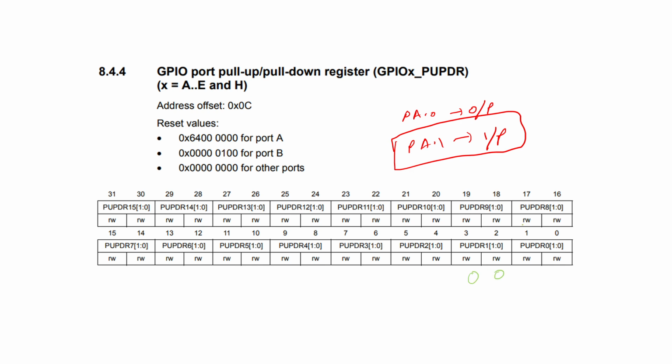According to the way that I have told you, when writing into the registers, using AND assigned with NOT, along with OR assigned with, you have to use only these to configure the registers. These are the rule of thumb, because using any other combination, like directly assigning it, will always erase the existing configurations, which is not desired for any embedded application.